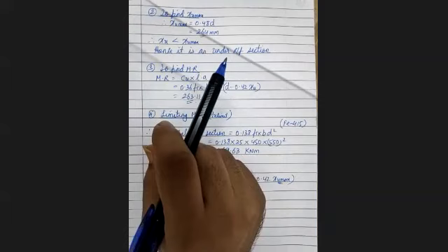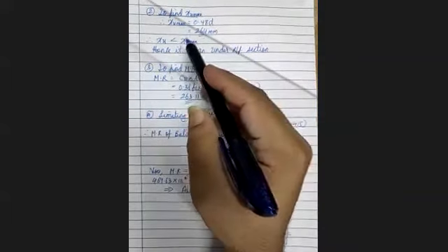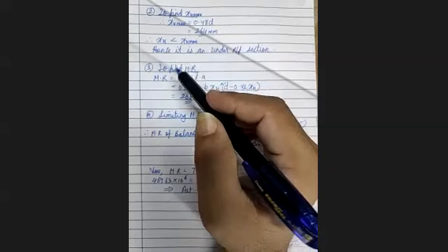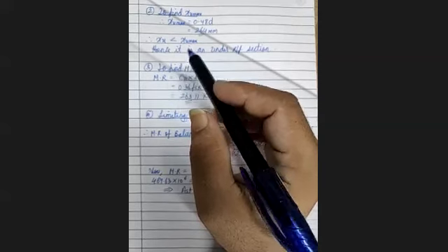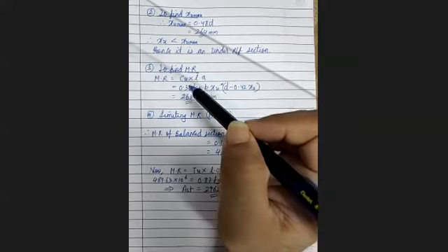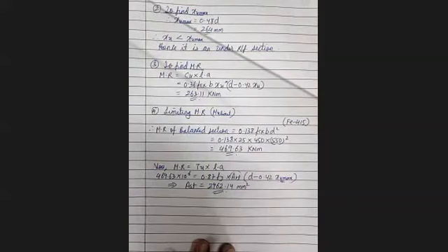So remember, it will be an under-reinforced section. But if Xu is more than Xu max, then you have to find out MR by considering it as a balanced section, that is Xu equal to Xu max. Consider that and find out the MR. Is this clear, everyone? Yes, is this clear? Yes. Yes sir.